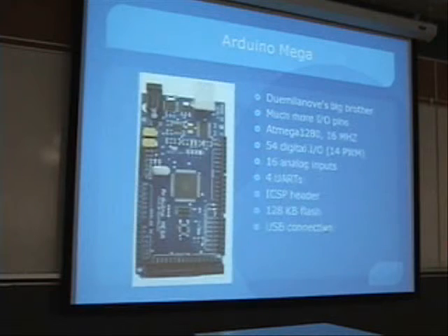Sorry, could you just go back one second? Sure. On communications there, we see it's TX3, RX3, TX2. So there's 3 serial ports, and yes. And then I think it's I2C or everything there. I think the 324 or 328 has 2 serial ports, and the 168 we've been using has 1. No. Is that correct? No, both of them have only 1. The 328 and the 168 are pretty much exactly the same, except it has more flash memory and RAM.